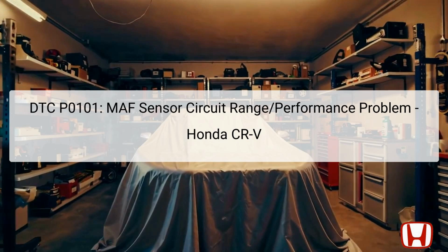If the MAF sensor is not functioning correctly, it can lead to various performance issues, including poor acceleration, increased fuel consumption, and potential engine misfires. Properly diagnosing and addressing this DTC is vital for maintaining optimal vehicular performance and emission standards.